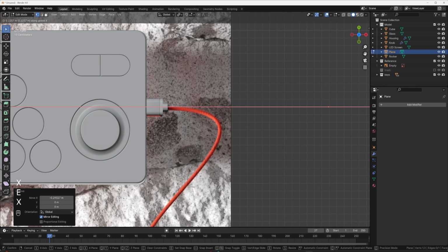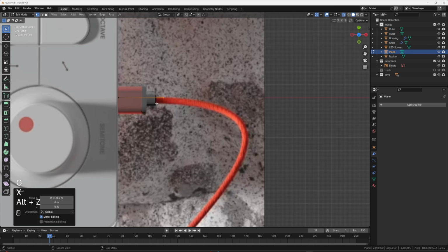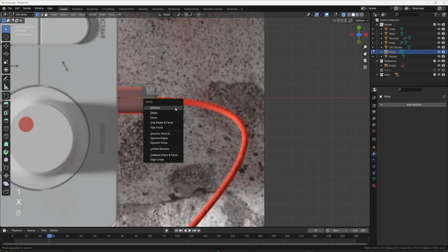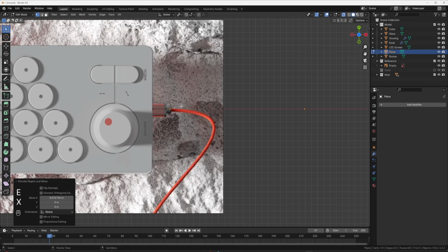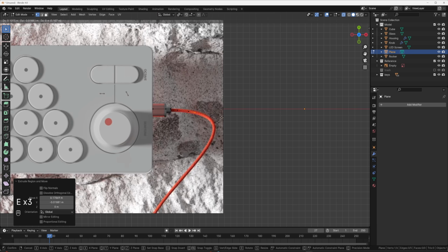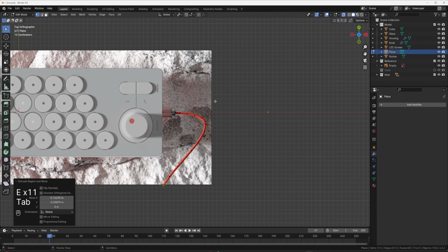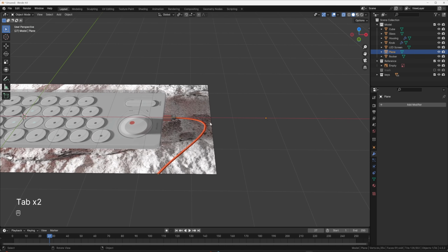I'm going to EX. So now what you're basically getting is, I'm going to go into X-ray mode. Now we've got a line with that EX. I'll just do that again so you can see. We're going to delete that vertex. So that one that we took, EX, I'm going to put EX again, just so this is straight. And now you can just press E and move this along, like so. All the way down. You can make this as long as you want, depending on your shot. And now that we have all these, this is just a segment of lines and mesh.